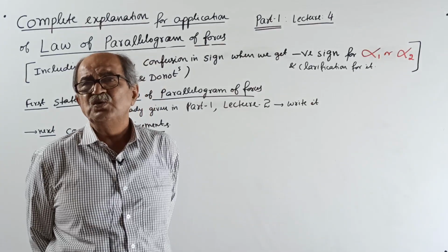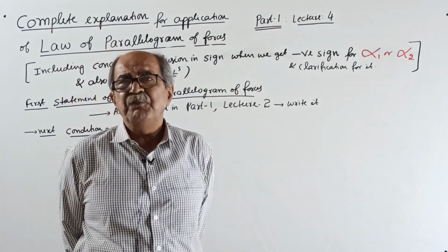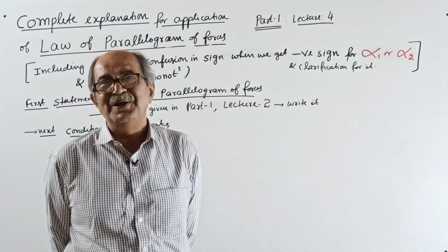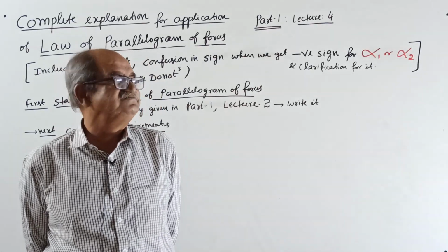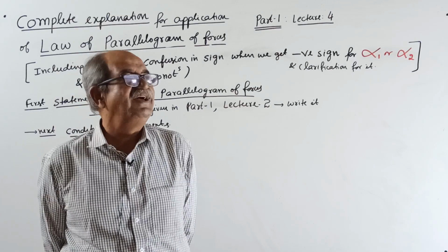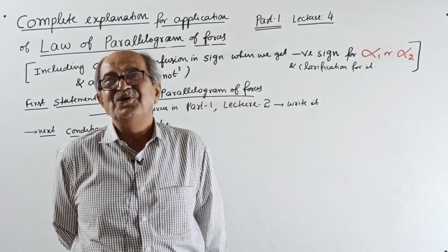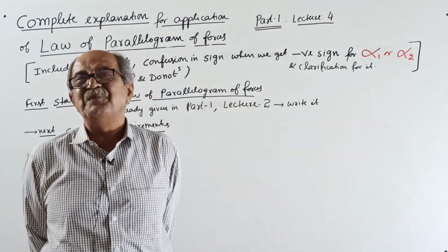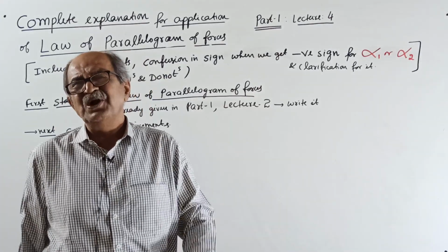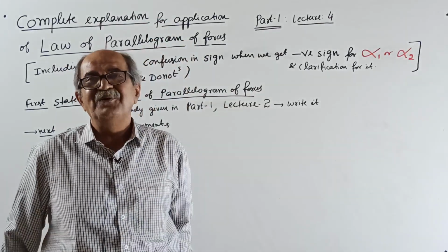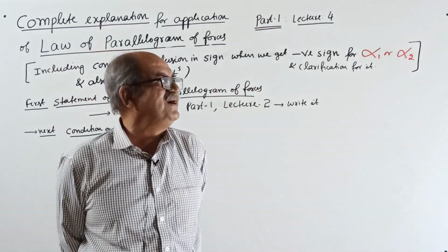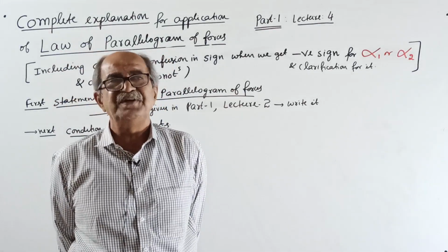Then R equals the square root of P1 square plus P2 square plus 2 P1 P2 into cos theta. I will tell why I said F1 earlier. In steel structures, when you go for eccentric connection, we don't call it P1, we call it F1. I solved plenty of questions, and it suddenly came to my mind. So R is the root of P1 square plus P2 square plus 2 P1 P2 into cos theta.